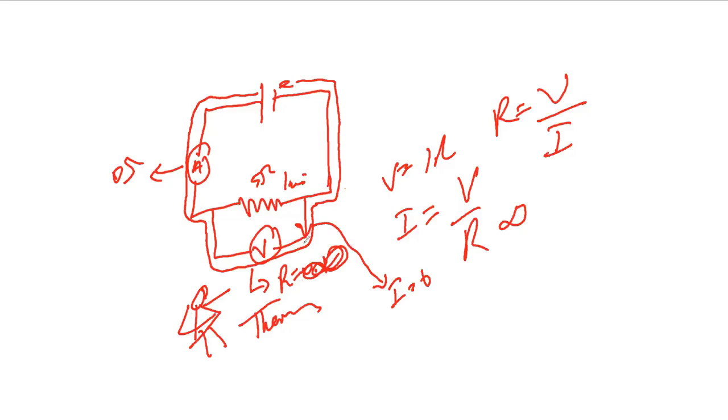What about ammeter? Ammeter is 0 ohms, right? Yes, ammeter will have 0 ohm because if there is some resistance, then some potential drop will also occur in this ammeter, and that will affect the measurement of the current. That will not give me the exact value of resistance because some sort of error will also be present in this circuit. Oh, I get it. Okay, so.